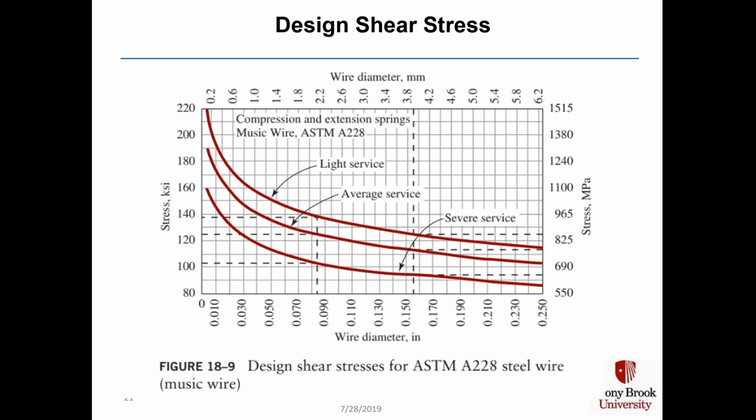And your job is to calculate the actual stress in your spring, determine which of the 3 curves is relevant to your design situation, and as long as these curves are above the data point you calculate for the actual location of the spring stress on this graph, you're good to go. On the other hand, if your calculation of spring stress is above the relevant curve, it means you're going to have to change your design in some manner, or your spring will break before it gets to its design life.